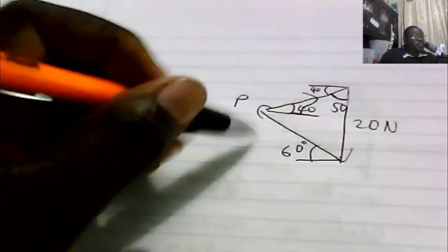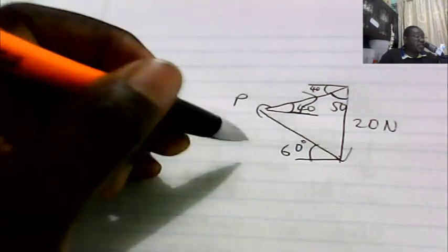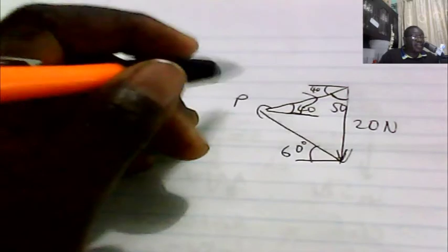We've got the 20 Newton force going down. That's 20 newtons. And then we've got P going up. P is at 60 degrees to the horizontal. And then we've got Q, which closes the triangle, moving upwards. And the angle here should be 40. So if this angle here is 40, then this angle here will be 40. And then this one will be 50. You have got to draw these vectors to scale. Remember, you draw these vectors to scale, and you always draw them head to tail and find out what you are going to get.